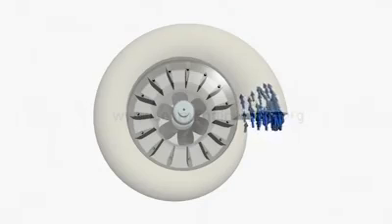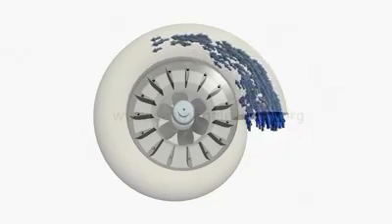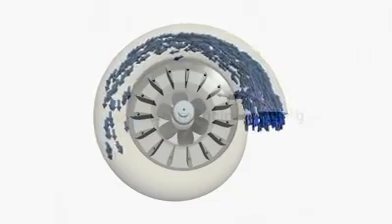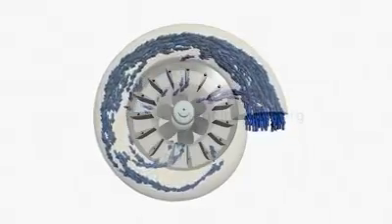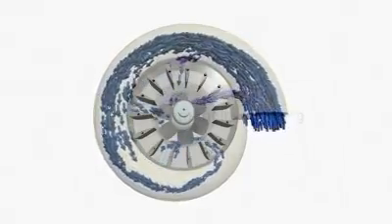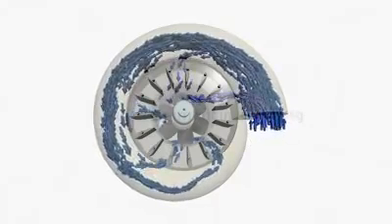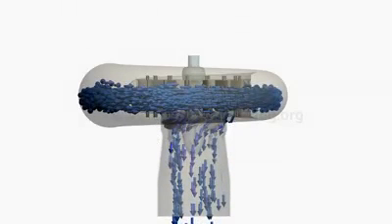In Kaplan turbine, flow is entered through a spiral casing. Decreasing area of casing makes sure that flow is entered to the central portion, almost at uniform velocity, throughout the perimeter. Water after crossing the guide vanes, passes over the runner. Finally it leaves, through a draft tube.